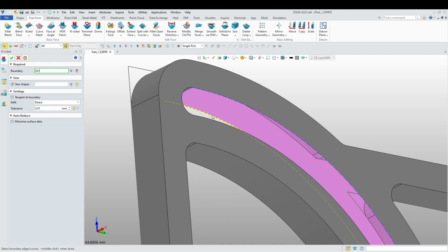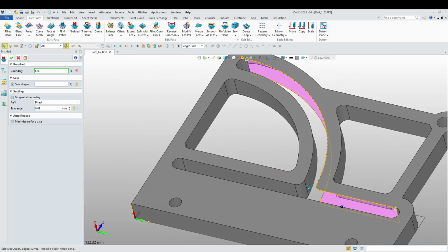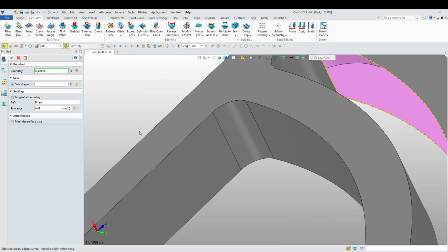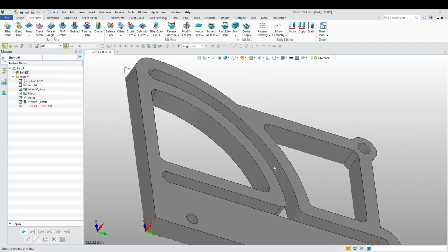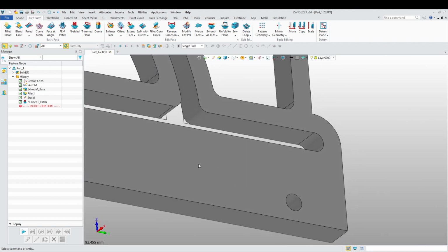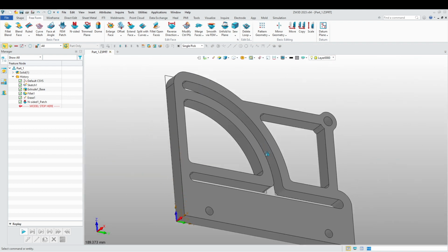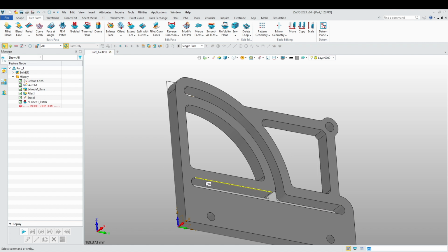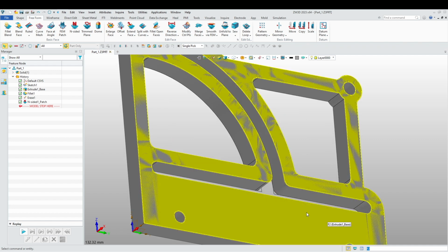Okay, so there we go, here we go, there we go, and there we go. So with inside it, we choose the edges that we need, create our face, and as you can see, it has eliminated those edges over there. So now when I create a constraint tangent, all right, it will identify this whole face. All right, so when I move the part, you can move freely back and forward and up. Without doing this, it won't be possible.